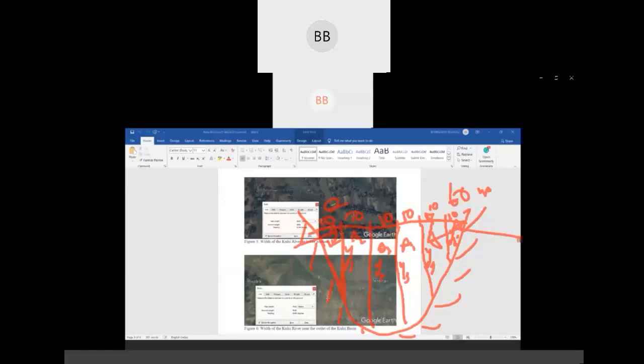And then velocity. What we have studied is that the velocity at the bottom of the channel is 0, it increases, and when it reaches the top or surface, it again decreases. So this is the surface of the water. What people say is to take the average of 2 readings, that is at 0.2 of y and at 0.8 of y, at 2 sections, and then you take the average.